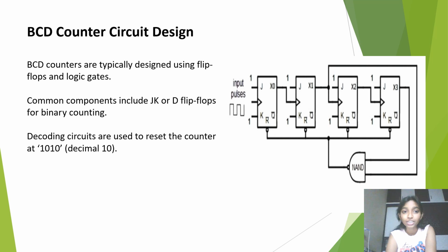BCD counter circuit design. BCD counters are typically designed using flip-flops and logic gates. Common components include JK or D flip-flops for binary counting. Decoding circuits are used to reset the counter at 1010, that is decimal 10.